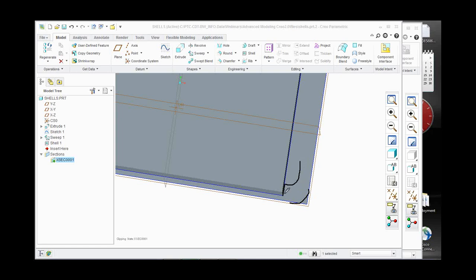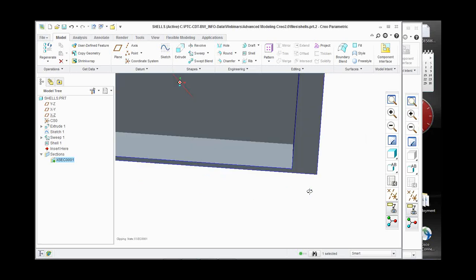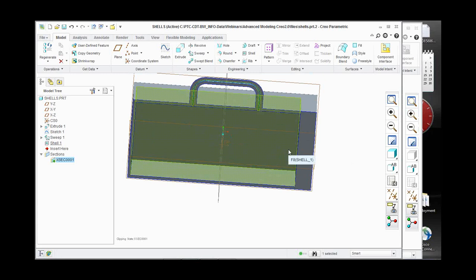You essentially have this little knot, or this little step in here, that doesn't work for you. So if you're going to put in multiple thicknesses, the best way is to put in a round like this after the fact. It really is the only way to get something done. If you have a round before and you put in multiple thicknesses, you'll get this weird step, so what you probably should do is get rid of the round and then put in the rounds after the fact, and you'll get a good result. Just a little bit of advice when you're doing rounds and multiple thicknesses in shells.